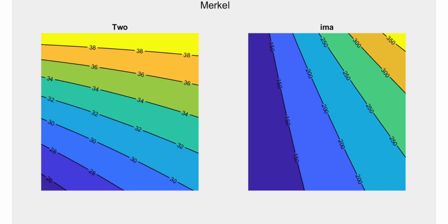The cross-flow Merkel number calculation according to the Merkel approach gives two graphs as output. It's the water temperature through the two-dimensional cooling tower. You can see it enters at a constant temperature, and as it flows through the cooling tower, falling down, it gets cooled by the air entering from the left.